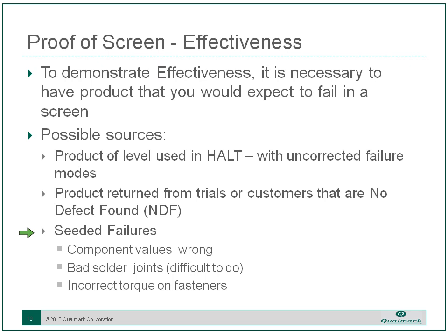That can be tricky. It's really hard to do a bad solder joint on purpose that's so bad that it'll come apart in HASS and be something that would have affected product life. You certainly can look at component values that you may be able to substitute in that the unit will function at room temperature. Capacitor values you can cut in half or double part of the time and not really see anything during normal operation, but you would expect HASS to catch that.